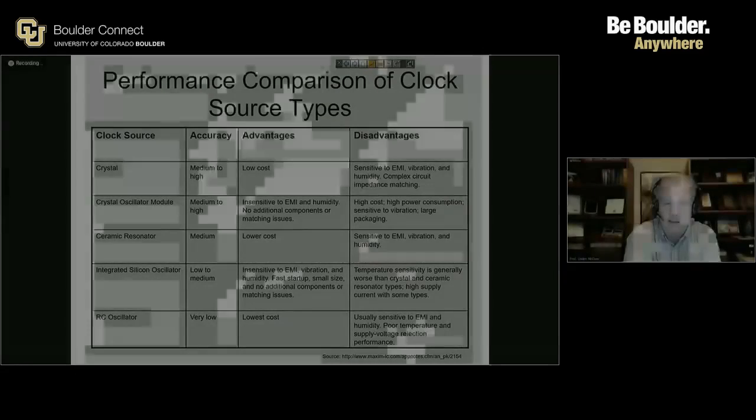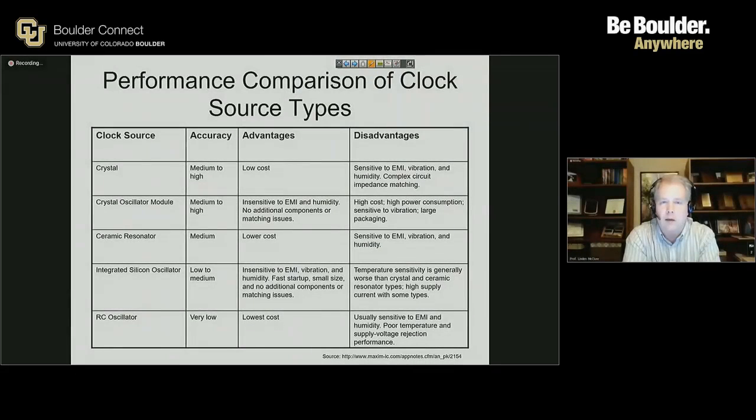What the exact accuracy is, the cost of your system design is most important. And so if you can design in elements in your software design which can accommodate variations or fluctuations in your clock source, then you can get away with a cheaper design, which is ultimately allowing you to be more competitive in the market.